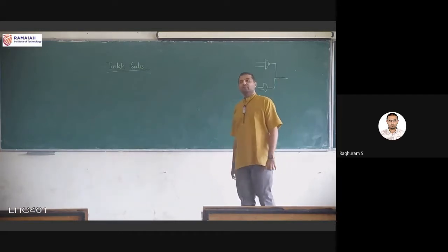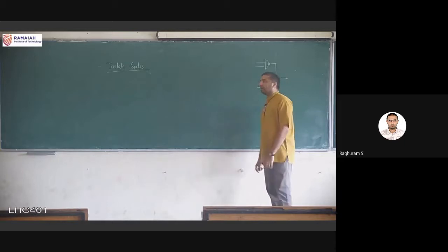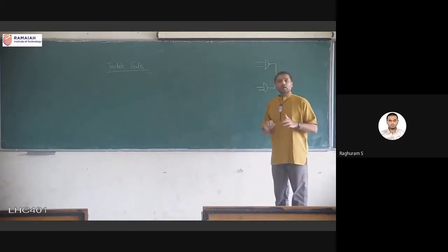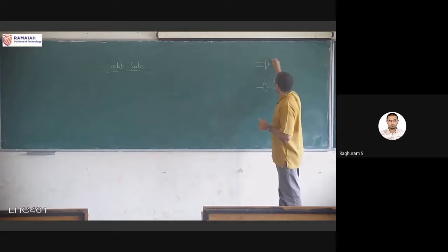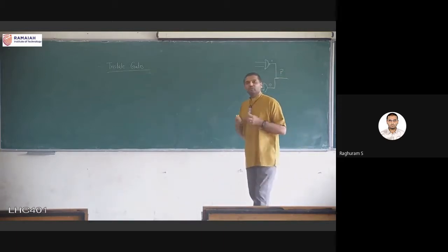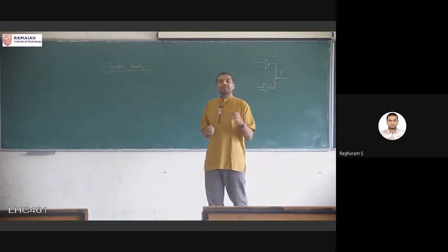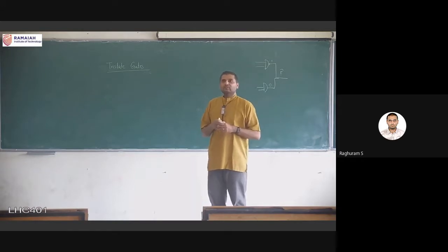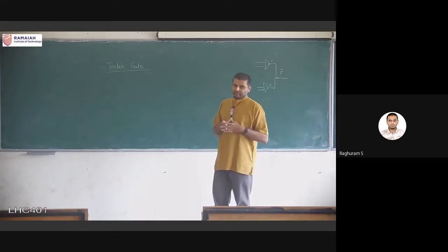Another reason is that the gates' outputs could have different values. Suppose this gate is producing 1 and this gate is producing 0. What is the value of the actual wire, or the electrical signal value? Because one is at VDD and another is at ground. Now what is the value of the output? It will be at a very bad or indeterminate state.